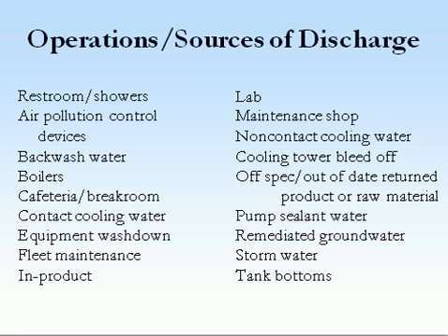There could be other sources that aren't listed on this slide, so you want to make sure that you ask the industry if there are any other sources that you've not asked about or that they've not mentioned that might be discharging wastewater, and you can ask that question several times. Sometimes they've just forgotten it's something that's off, tucked away in the corner. And then as you're going around yourself, make sure you watch for that. Is there water anywhere else that they've not discussed with you? Ask about it.